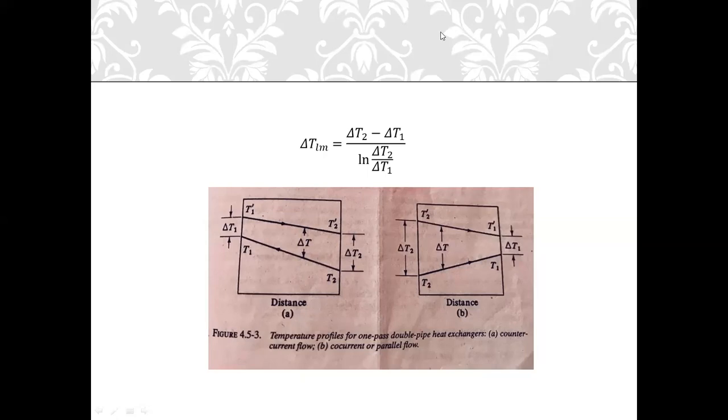So let me annotate your original formula for convective heat transfer, which is Q equal to UA delta T. It's not written as delta T mean, but simply delta T, which is just the difference of the temperature of the wall and that of the bulk fluid. This will now be changed to delta T log mean. Okay, it is very important, class, that you understand when you use this formula and when you use this.